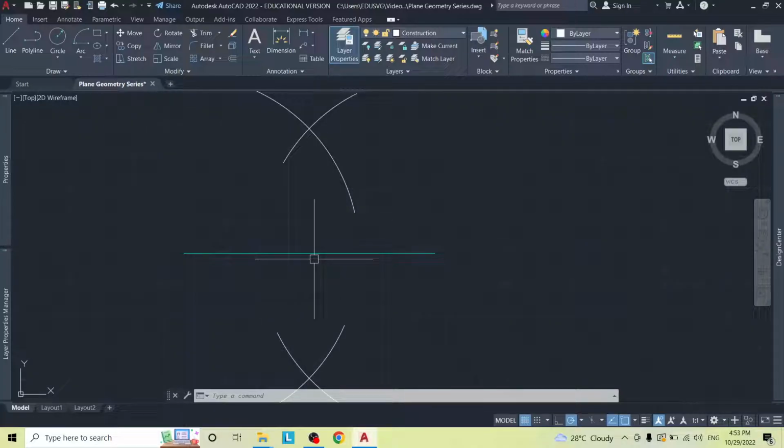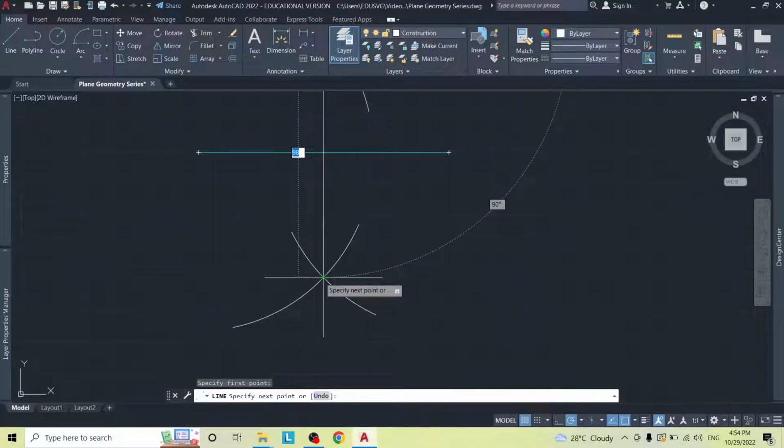So you either need to know the length of the line so you can work out what more than half is, or you can just look at the line and determine what more than half is. Just reuse that same measurement. So we are basically finished. We just have to draw a line from the intersection of the top arcs all the way down to the intersection of the bottom arcs.